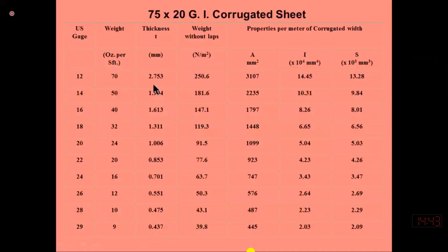So we can forget this thickness easily. Instead of representing the thickness in millimeters, we refer to it with another unit, which is referred to as a gauge number. If the thickness of the element is very small, instead of referring to the thickness in millimeters, we refer to it as a gauge value. The more the gauge value or gauge number, the lesser the thickness of the sheet.